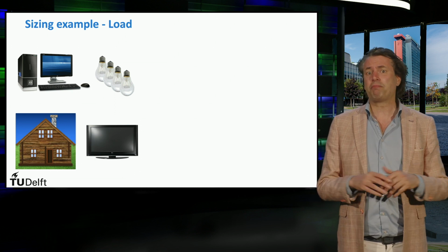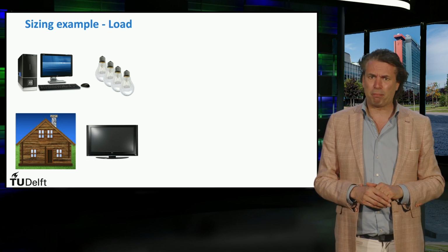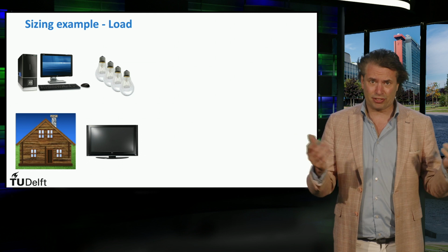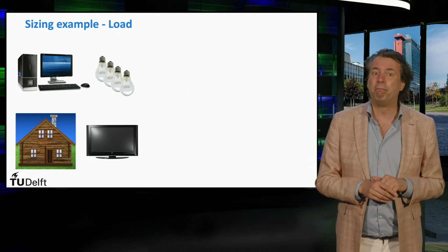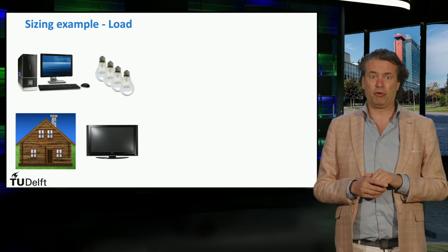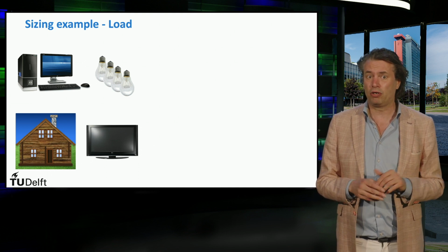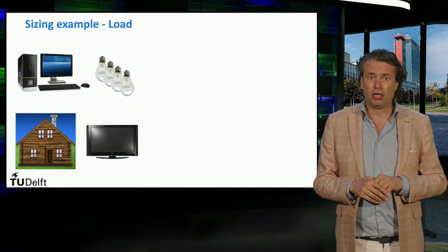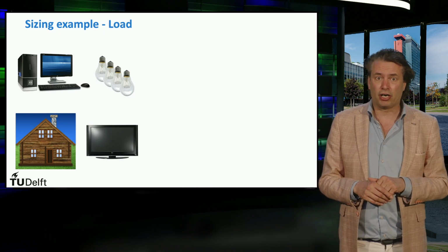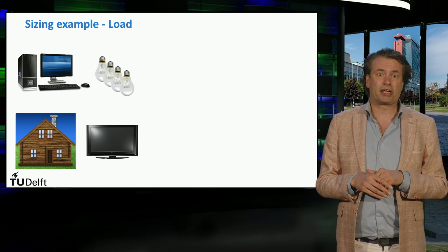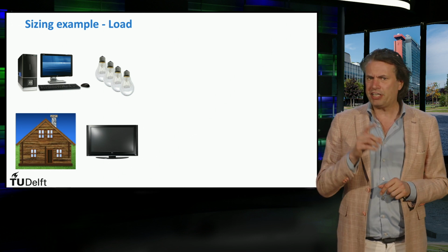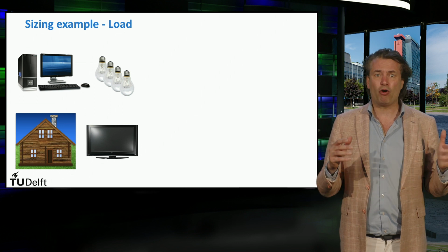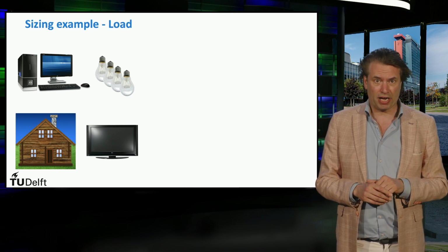We here use a simplified design strategy that can be applied to both grid-connected and standalone PV systems. In this design strategy, only the bare minimum input requirements are known, such as the PV module type, the loads used in the PV system, the charge controller, inverter type, maximum power point tracking algorithms, and the specs of the battery. For this simplified strategy, many oversimplifications are applied.